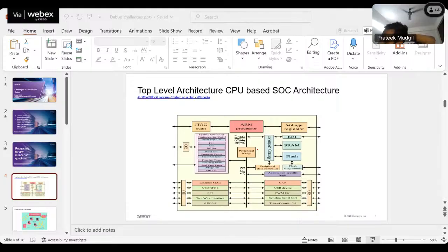So these things are happening inside the same die, right? If we see the clock to clock path, from this path to this path, the skew, when we meet the timing, we do the STA, right? PrimeTime runs and we meet the timing.